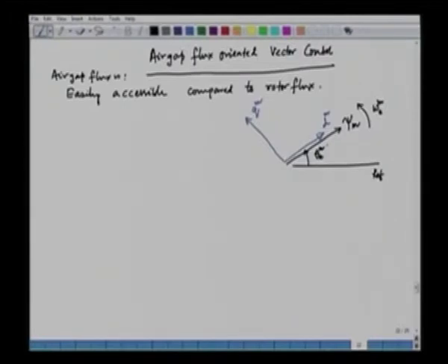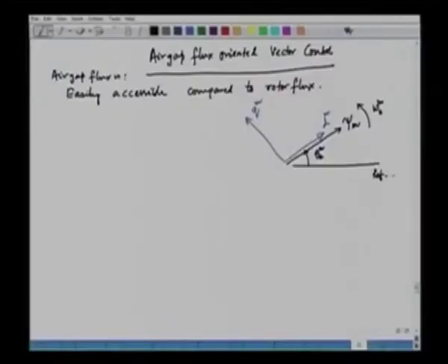So, what we do here is that we have to find out theta e m, and if we know theta e m, we can transform the variables in the air gap flux reference frame to the stationary A, B, C. We have phase A here, maybe phase B 120 degree phase away from this, phase C 240 degree away from phase A, and hence if we know the angle theta e m, we can evaluate IA, IB, IC in the actual phase variables of the induction machine.